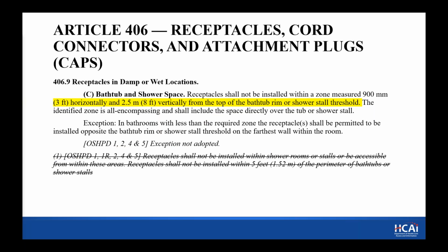Receptacles, same requirement is being added now for the receptacles for the bath and shower space. Previously it was 5 foot, now it's 3 foot. It has to be 3 foot from the edge of the shower or tub or stall.